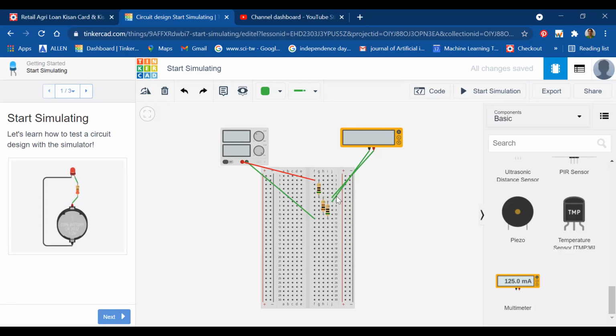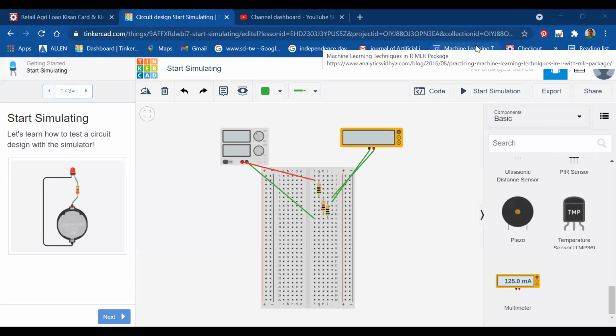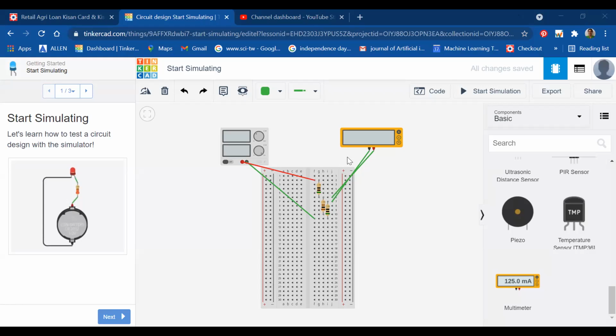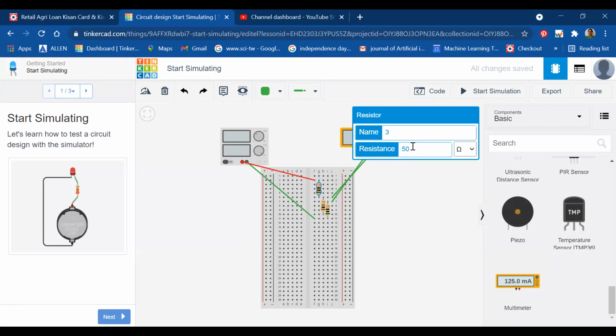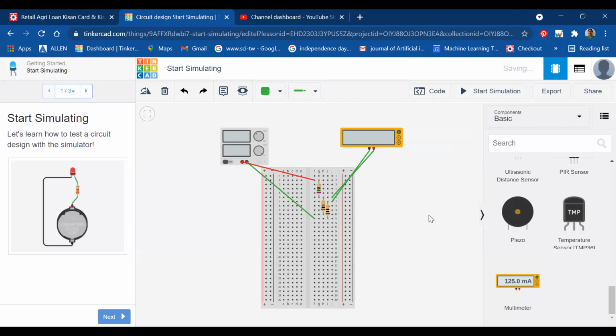So now I am going to shift my milliammeter towards the I1 position and shift my power supply towards this position and find out the value of the current. Or we can take different values of this resistance R1 and check the values here, one by one, because when we change the connections, we can take the reciprocal of all these three circuits. So let's take case 2 here, and I am going to change this 50 ohms to 75 ohms, and then cross check the value of my current here, and tabulate the values.